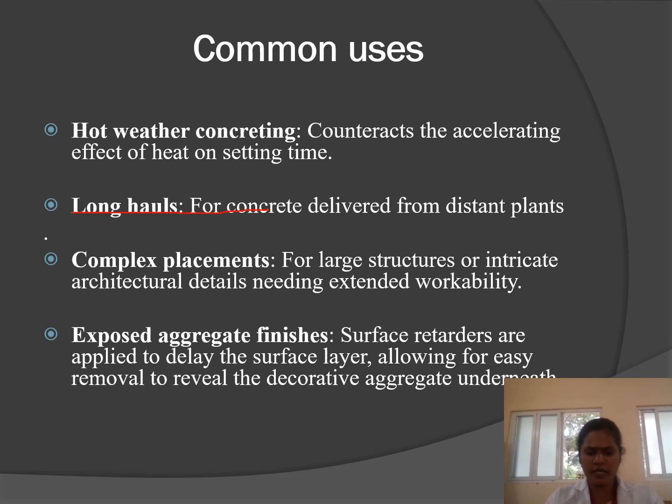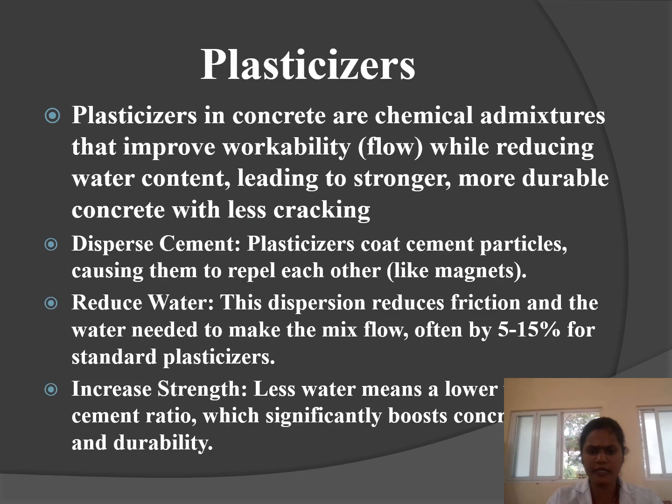Exposed aggregate finish: surface retarders are applied to delay the setting of the surface layer. This allows easy removal of the surface layer to reveal the decorative aggregate underneath.